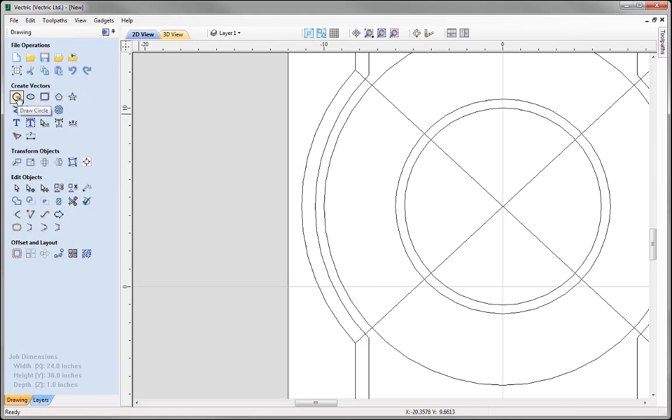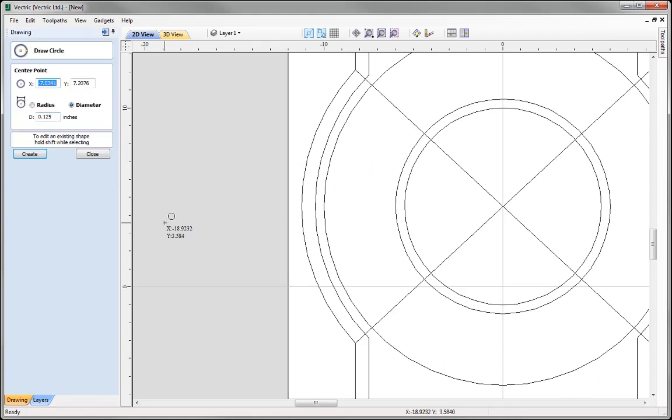So I'm going to go into the Draw a Circle option, and to do this, what I need to do is I just need to wake up this point here. So I just hover over this point, and I'm just going to come across the horizontal. I'm going to wake this point up here. Okay, then I'm going to come back, and as I travel over that, you can see that we now have the halfway point, and I can see that because my cursor's changed into a crosshair, allowing me to snap to that point. So I can now draw out a shape.